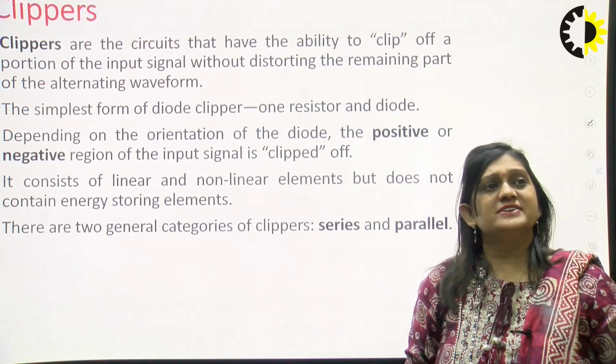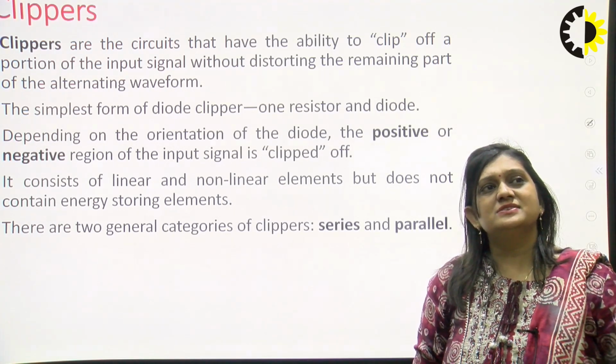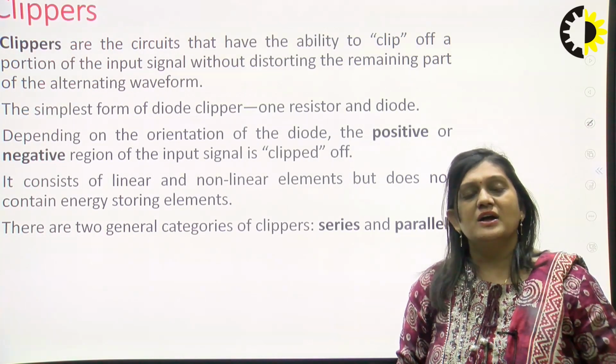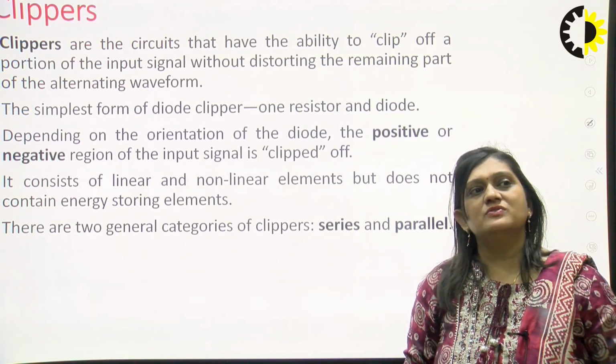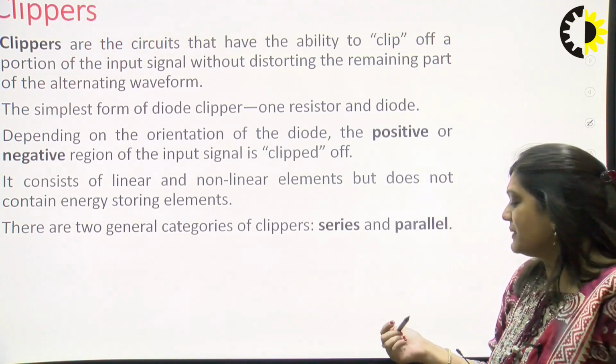So the first question that arises is, what is a clipper? Clippers are basically circuits that have the ability to clip off a certain portion of the input signal without distorting the remaining part of the alternating signal. Clippers may be of two types, series clipper and parallel clipper.